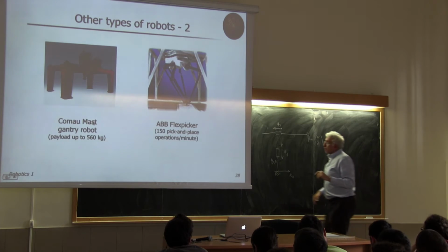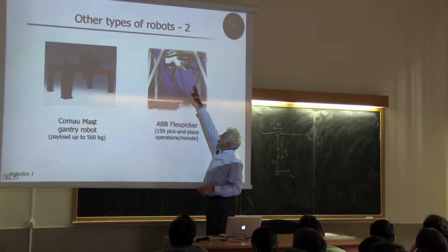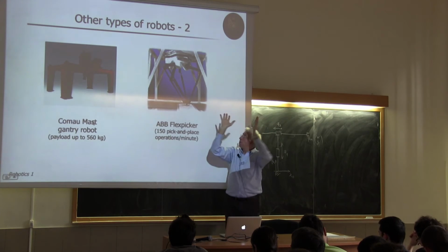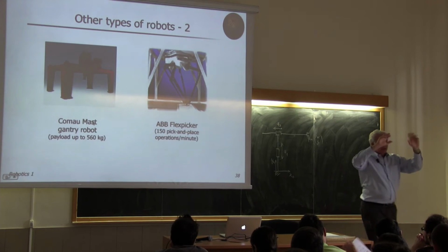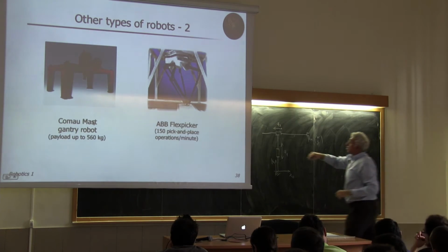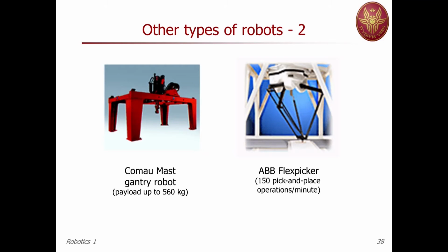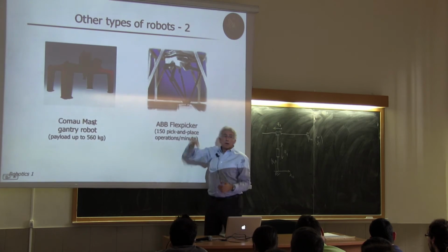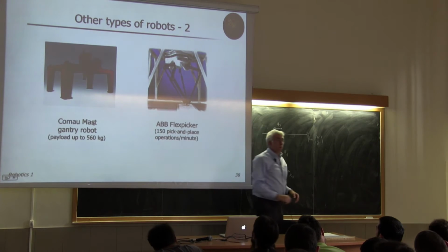In fact, we will see now a video showing the mobility, but the 6 actuated joints are all placed in the white box on top. So there are 6 motors, each of which changes the angle of the first link connected. All the rest is purely passive. There is no motor at all, here at the elbows, here at the passive joints connecting to the end effector, which is this plate below.